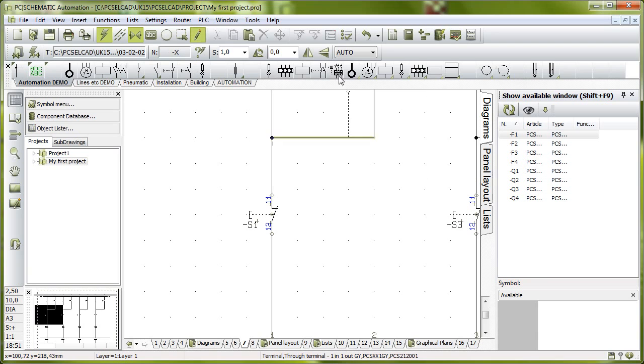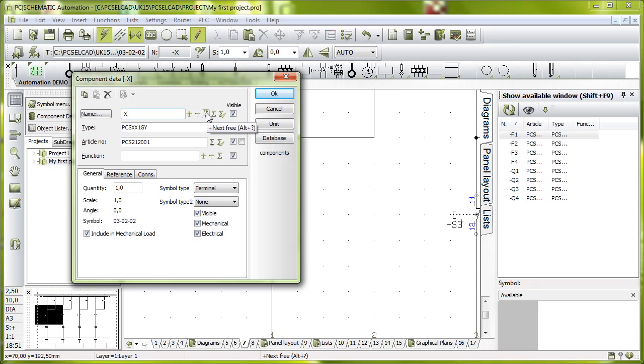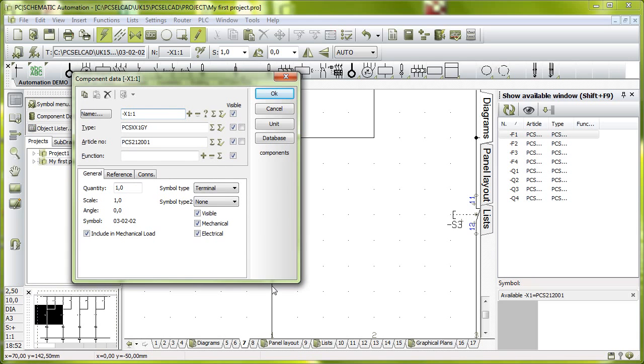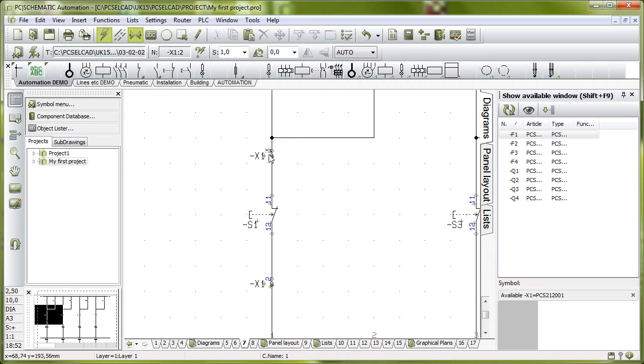That means that if I add a terminal here, we can call this x1:2 and call it position 1. And I can go here, and this one will be position 2. I can use a question mark. And now you see that this side here is okay because the green points downwards. That means out to this external component.